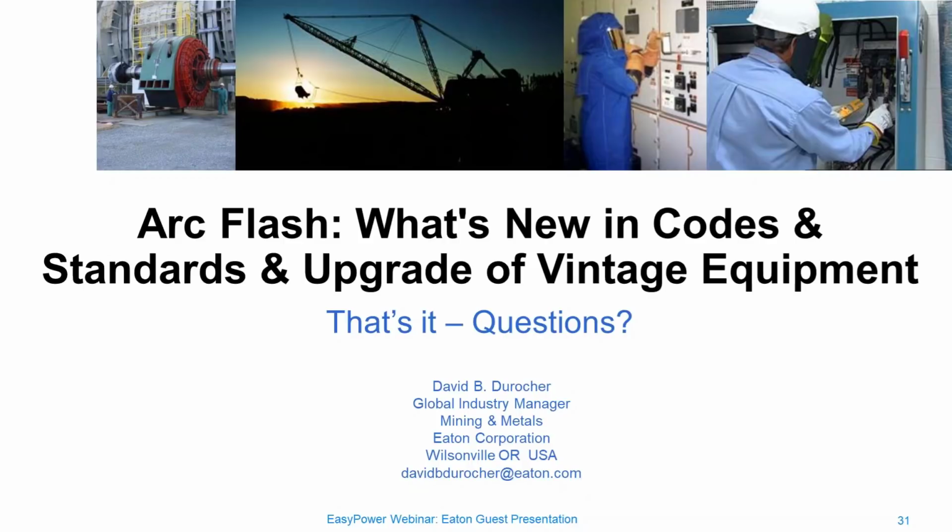My view is that when we're talking about electrical workplace safety and PPE and working on or around energized equipment, then 70E would really take precedence there. The 1584 is really just a calculator. It's a way to calculate and determine what the incident energy is. An owner might decide to be prudent.